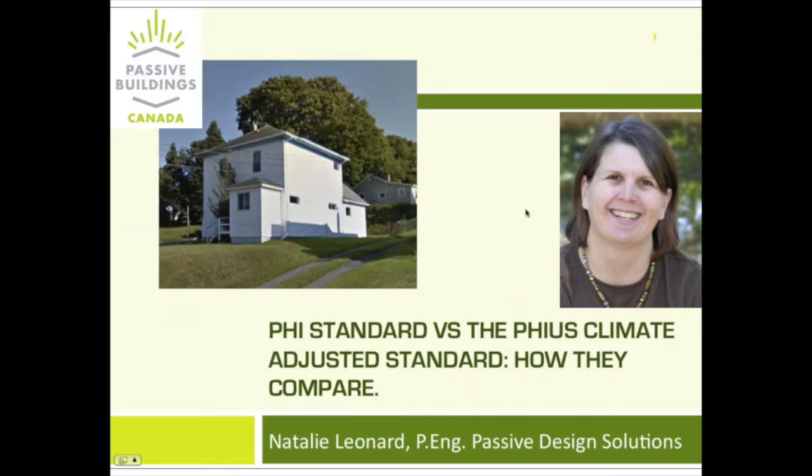Great. And Peter Schroner asks, was the heat pump domestic hot water drawing heat from the indoor air and adding to the heat load an issue? Yeah, another good question. So there's a mini calculator, and I believe this is in the resources page on PHIUS as well, that basically says that for a certain time of the year, you're definitely drawing heat out of the building and cooling the building, which you're having to replace with electric baseboard heat.